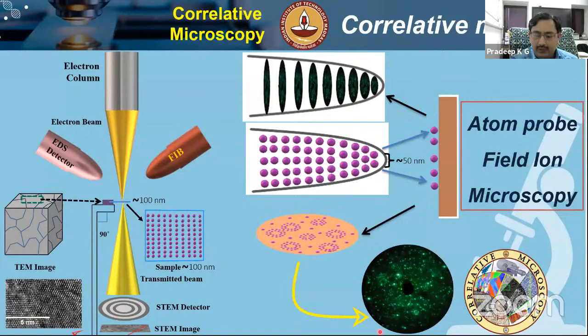But by doing field ion microscopy, we already know the exact crystallographic orientation of the grains that are emitting these atoms. So the missing atoms from the detected region can be iteratively identified for their positioning using this computational approach. We can then go back and see if a real lattice reconstruction can be built, and it can be utilized for cross correlation with their chemical distribution.